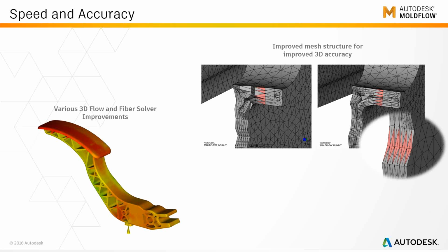The other thing you'll notice is the structure of the mesh in the prior release. We would typically see the diagonals going in the same direction. That can numerically skew results a tiny little bit, and while the analysis progresses, small numerical instabilities can start progressively worsening the final result.